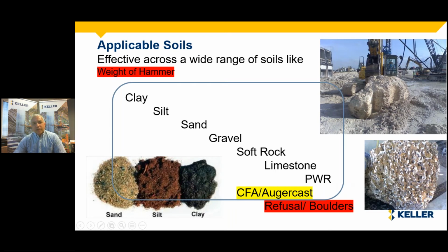Now, rocks, as you can see on the right side, are perfect. This type of rock on the right side is perfect for CFA, because when you drill your pile into it, as you can see in the upper picture, you're going to create this cylinder, and all these little holes are going to get filled with the mix. The cement is going to go into all these little holes, getting a really good friction addition. So instead of having bentonite or polymers filling those holes and then just pouring concrete like in a bored shaft pile, what we have is our cement, our concrete flowing into those rocks, getting that friction. And that's why in this type of rock, the CFA gets better friction capacity than the typical bored piles.